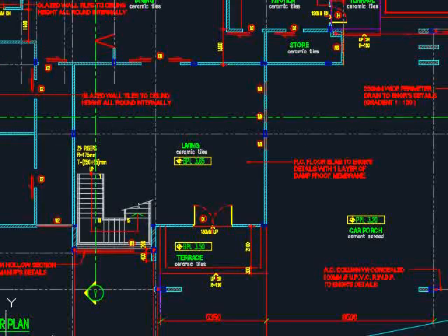The floor key plan also gives you information regarding the floor elevations. For example, proposed platform level 3.20. You have proposed platform level 3.50 and proposed platform level 3.65. This 3.20 is referring to the height from the mean sea level, and you will observe the differences in terms of the elevations for you to observe the rise and the drop of the slabs.